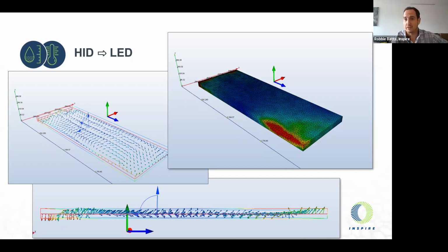If you look at the vectors, the velocity vectors of the air in the left and bottom diagram, you'll see that the arrows are everywhere. And where there's ridges and where there's arrows coming together, those are dead spots of airflow. That is going to become a problem from a humidity perspective. So let's say we do the reversal of the airflow inside the room, which is a pretty minor adjustment. And then we take fairly low cost in-rack airflow tubes and apply them. Next slide.